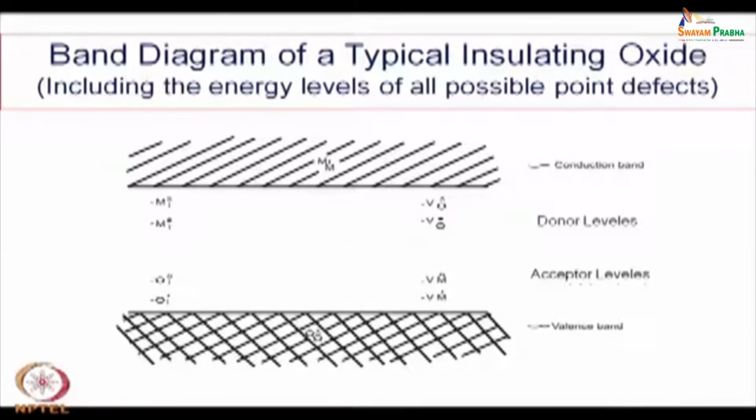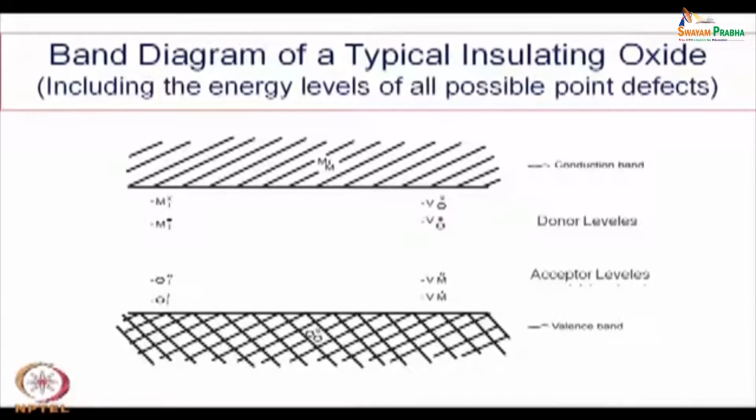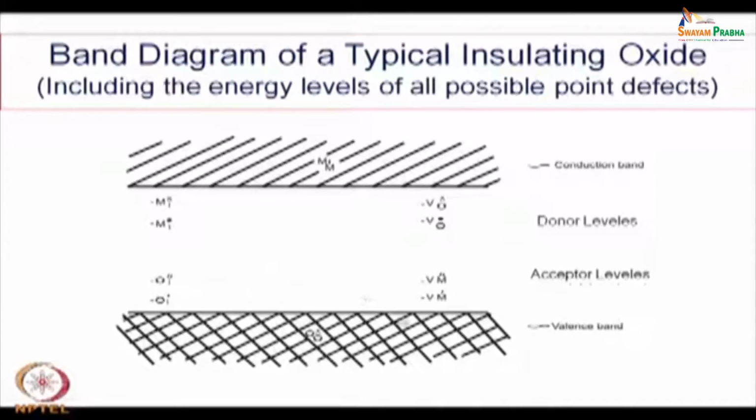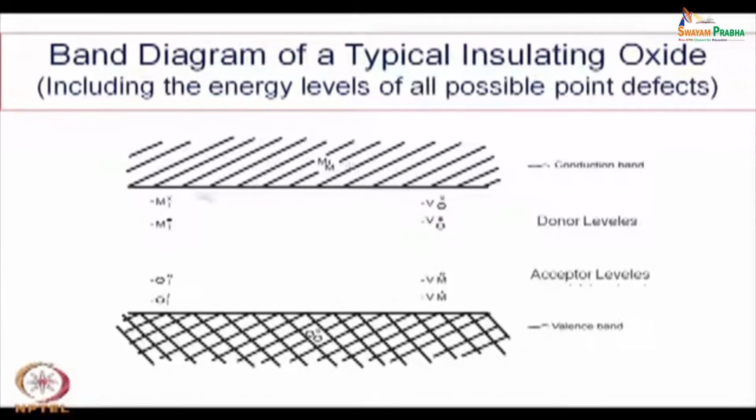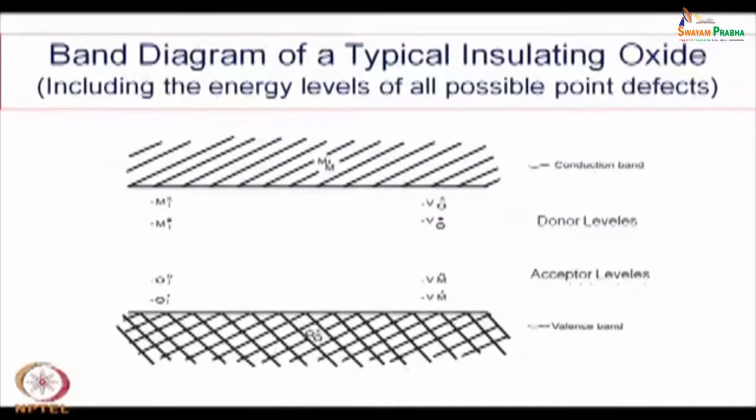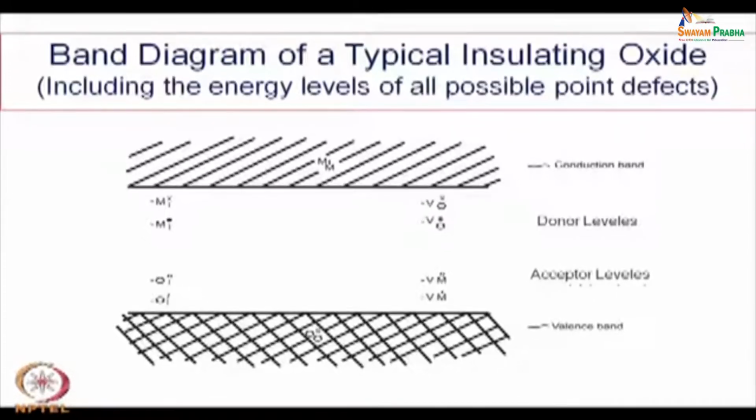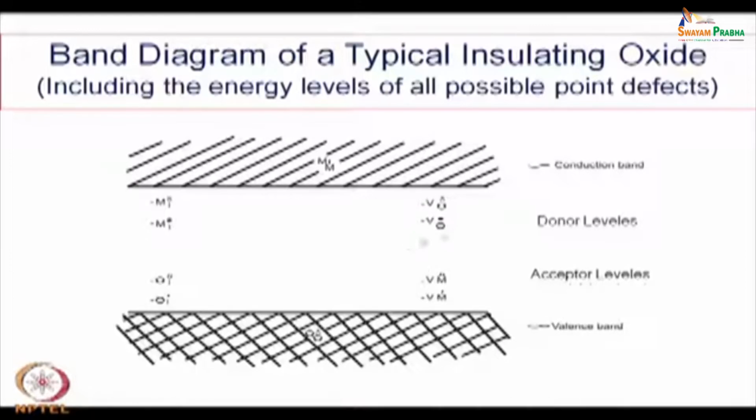So, this is a very important difference from the normal semiconductor when we talk about oxides. Without adding any impurity, you can have p type conduction and n type conduction, which we have discussed earlier, when we discussed defect formation as a function of partial pressure of oxygen. Some of them act as acceptors or p type conductors, but others act as n type conductors.